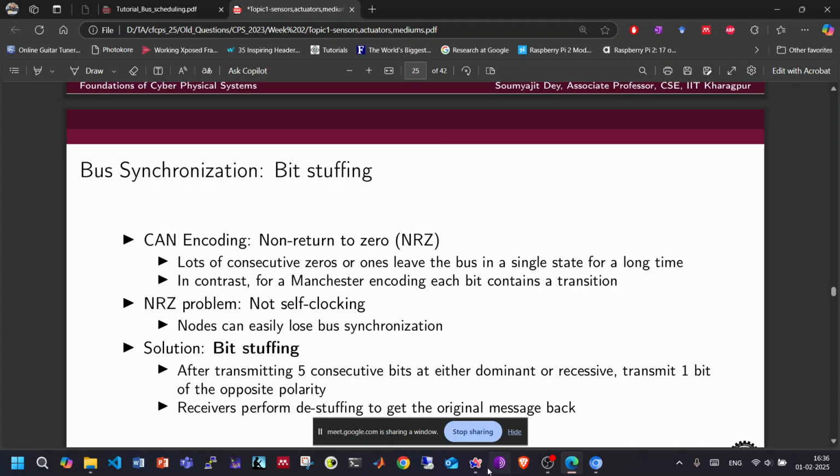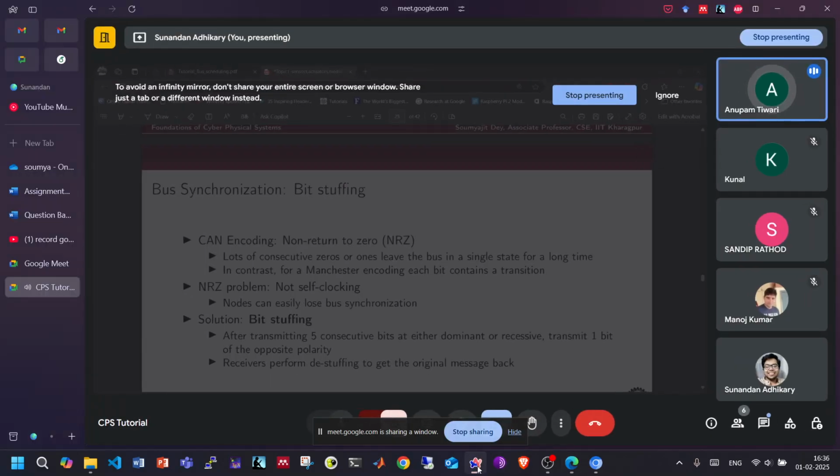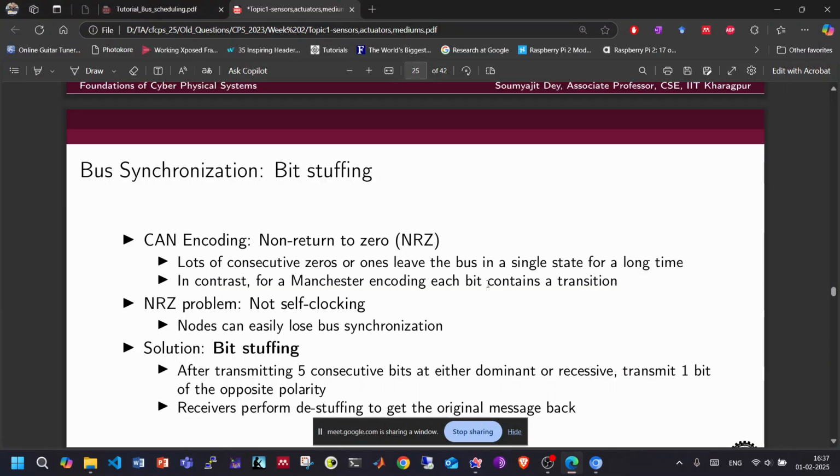Basically, the signal is always above what you say is the zero level. It is not bipolar; it is unipolar. So basically, in non-return to zero, you don't have a separate level when there is no transmission. You continue transmitting whatever you were transmitting last. So you don't return to zero when you stop transmitting.